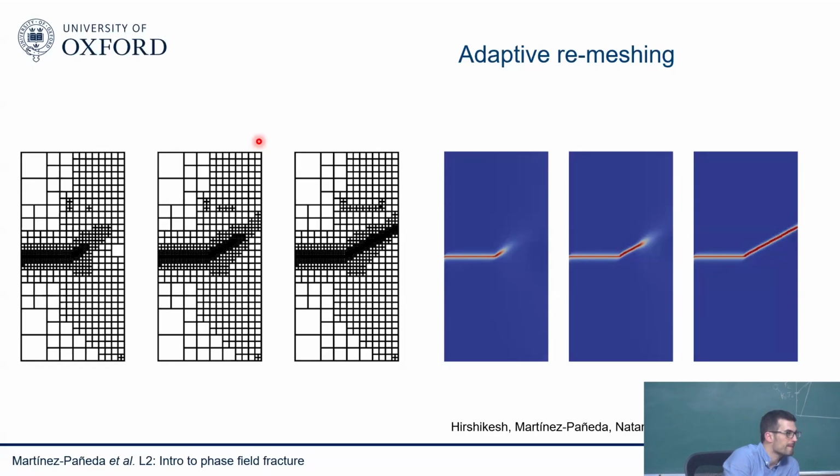So this remeshing is done at every step when the crack is propagated? Yes. So it will be like too much computation. It carries a cost. And we show in this paper, and everyone working on this adaptive mesh refinement area shows, that it is competitive, but not extremely competitive, because there's a cost of doing a remeshing every time, passing information from elements to elements and so on. So it comes at a cost. I'm just saying it as an option. Some people are working on this. I haven't put that much effort in there because I see a lot of complication for small gain, but that's a personal opinion. Other people will think differently.